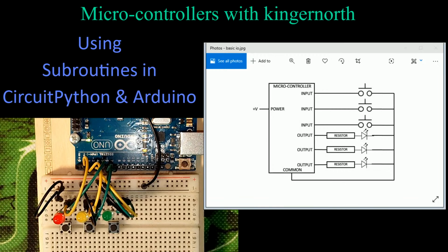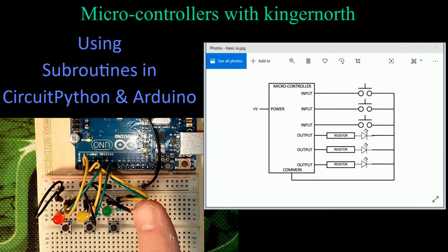In our case, today, we're using the USB cable to supply the power. So that works out fine. There are very few connections made. This is a very simple circuit. The resistors will depend on the board voltage that you're using and the type of LEDs. Here, I have my 3 push buttons, I have my 3 LEDs, and tucked in the background, I have 3 little resistors, which are hard to see. They're actually in behind there. There's a resistor there, if I move those wires out of the way.